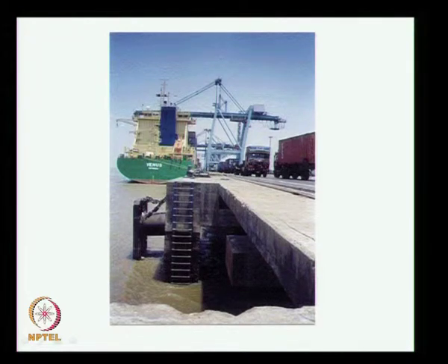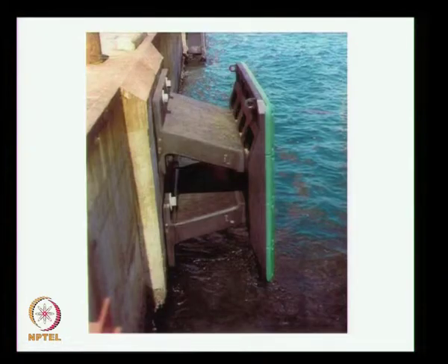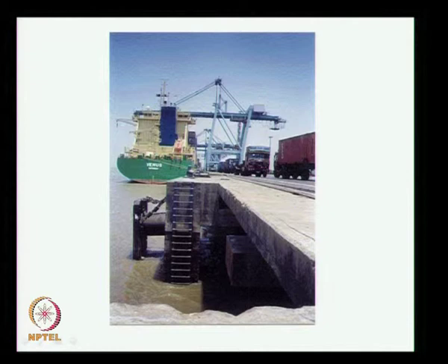which is used to connect the frontal board, which has a large weight. This is called a buckling fender. So these two arms will buckle. This is also a buckling fender, and this also will buckle. When it buckles, this height, let us say it is 1.5 meters, will get reduced to 0.75 meters; that much deflection will be there. Whatever is 1.5 meters will become 50% of that. Then when the vessel is not there, it will come back to 1.5 meters. So it goes in and out like this, which is why the life is only 10 years.